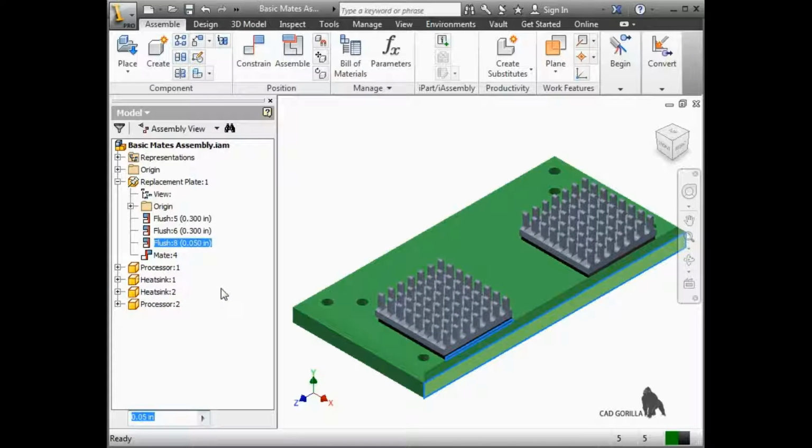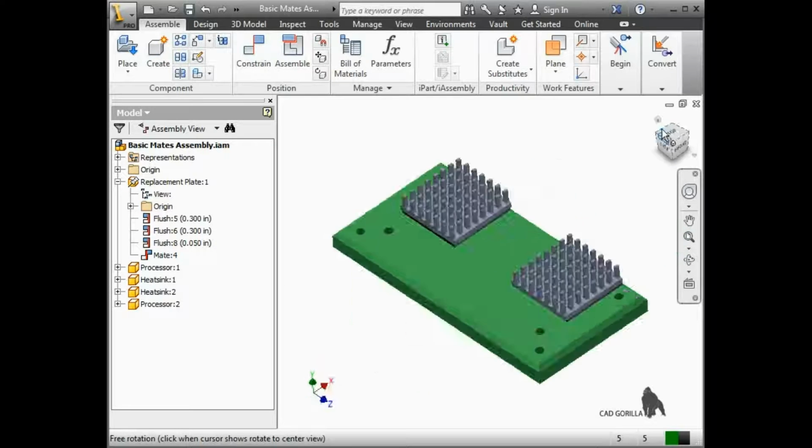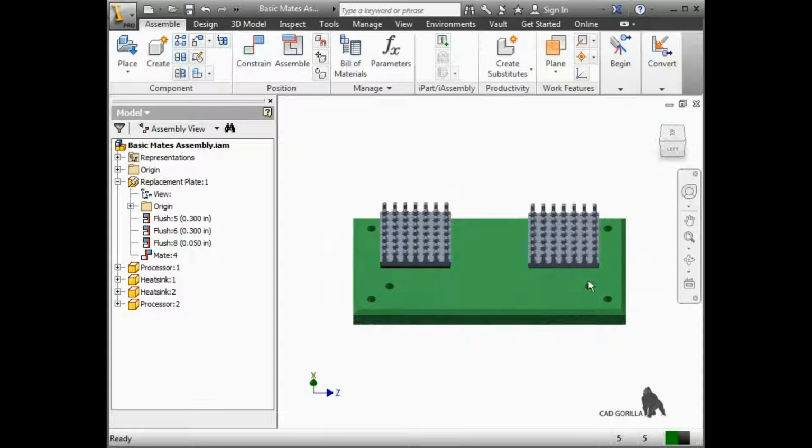If the parts move in the wrong direction, I can just edit the offset and make the value negative. If you look at the assembly from the top, you can see the end plates cover up the mounting holes. Rather than measure the distance, I'll just try some offset values until I settle on one that leaves clearance for the hole. When I click on the constraint, an Edit field displays at the bottom of the browser.